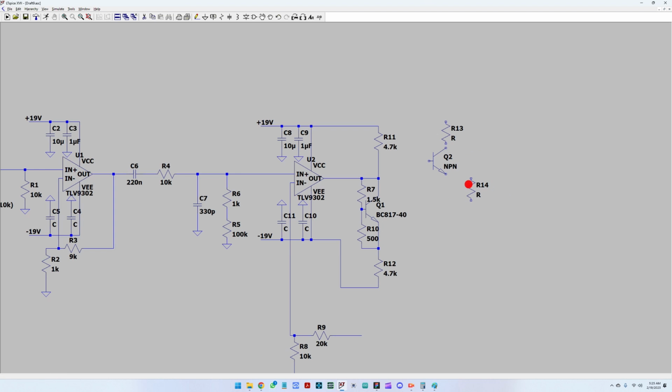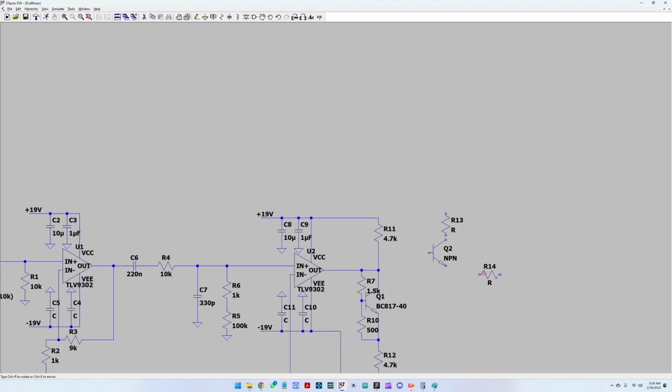Some developers put zero resistance here, but I always like to have a limiting resistor here, maybe a 50 ohm resistor, just so that I don't short circuit here by accident in the normal function of the amplifier. Okay, so let me connect this to the supply. Connect the transistor in the circuit.